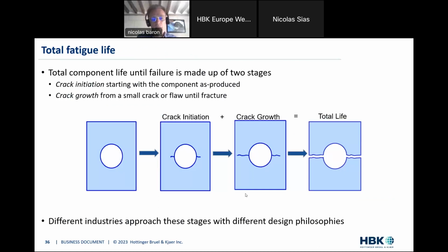There is firstly the initiation of the crack, and then once this has started, the crack will or will not, depending on the loading, depending on many things, might expand, might propagate, reaching a total number of a given length on your item. That will be the total life. So crack initiation in addition to crack growth is really what makes for the total life.